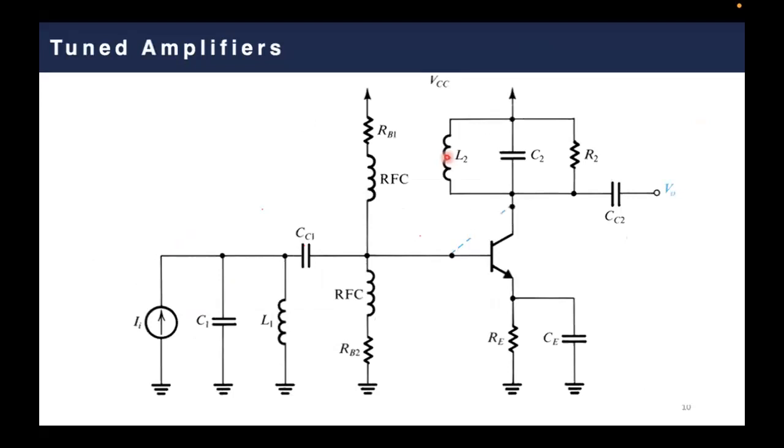And this is one of the very famous topologies used in a lot of transceivers, radio and RF transceivers, where you use a standard bipolar junction transistor in order to make your amplifier. Again, this is quite similar to the MOSFET topology. Here we have a common emitter topology. The input is fed to the base. The output is taken from the collector.